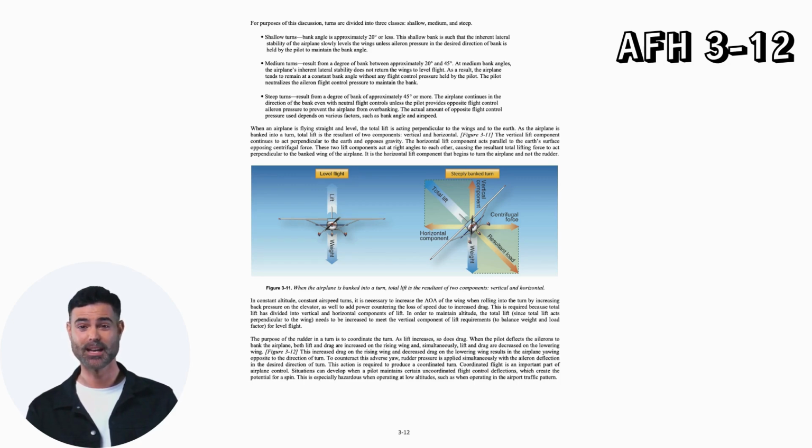Shallow turns: bank angle is approximately 20 degrees or less. This shallow bank is such that the inherent lateral stability of the airplane slowly levels the wings unless aileron pressure in the desired direction of bank is held by the pilot to maintain the bank angle.